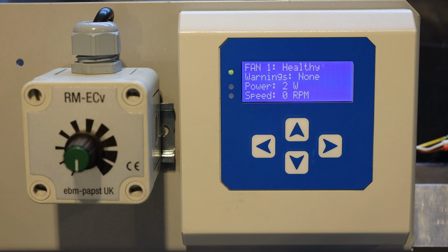Using an external client connected to the server terminals on the MDC, the speed of the fans can be changed by sending a command to a holding register. For this example, we will use holding register 4, which is the set speed of 0 to 100%. To verify the speed of the fans in the array, we can use holding registers CB08 and CB09, which will return the speed of the two fans in RPM. The first set point we'll choose is 25% of maximum speed.